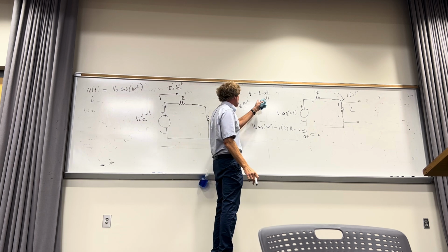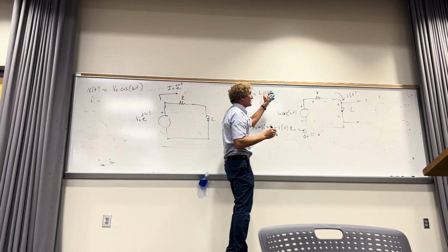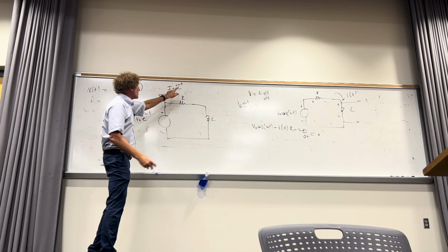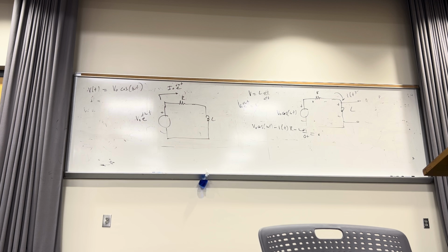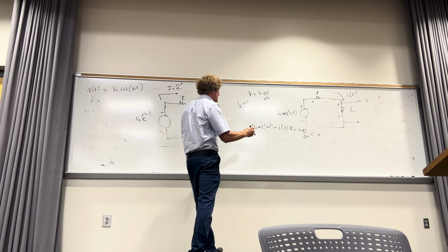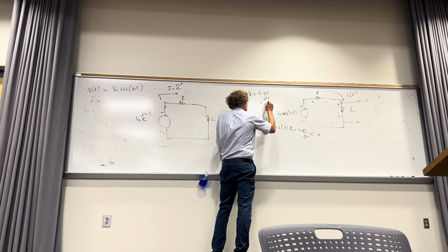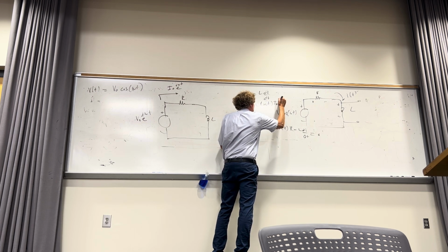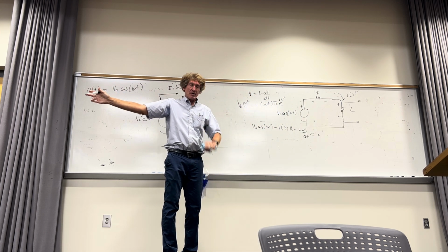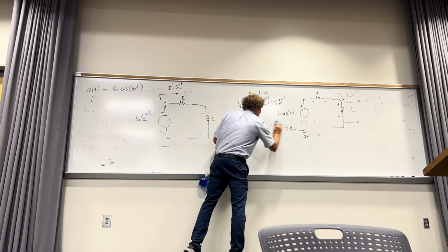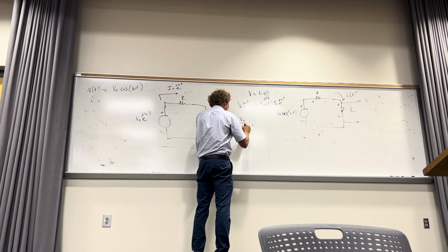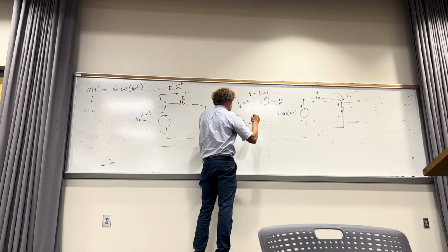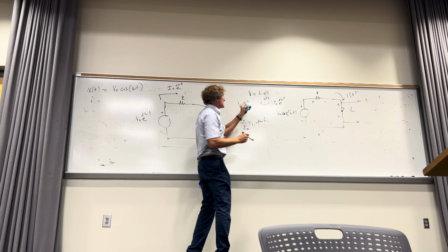Well, what current would be developed? That would be L times the derivative of I with respect to t. Just hang with me. You notice that I have I naught e to the j omega t as how it varies with time, right? What is the derivative of e to the j omega t with respect to t? j omega times e to the j omega t. So it's L times j omega times I naught e to the j omega t. This is the last point. Just go with me here and I'll let you go. I apologize for holding. So finally, at the end of the day, you can see that V naught over I naught for that inductor is just equal to j omega L, because the e to the j omega t's cancel.